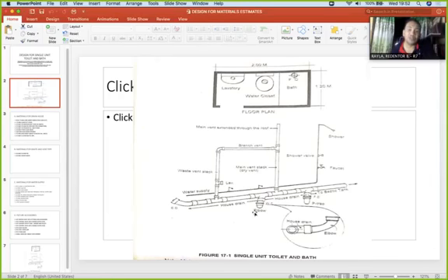Normally you use 4 inches, right? Because that's as far as you know. But as far as the plumbing code allows, you can use 75 mm. That's why sometimes there's a need to read the plumbing code, because without reading it, we cannot see.